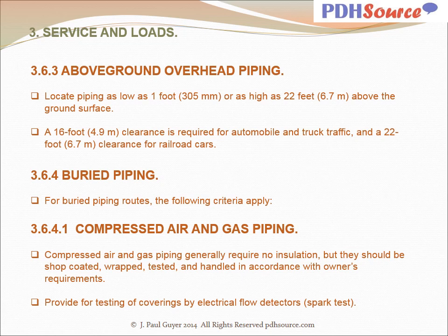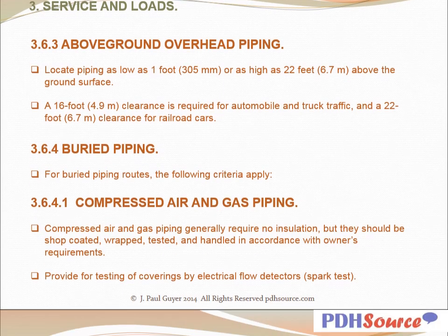First of all, compressed air and gas piping. Compressed air and gas piping generally require no insulation, but they should be shop coated, wrapped, tested, and handled in accordance with owner's requirements. Provide for testing of coverings by electrical flow detectors, spark testing.